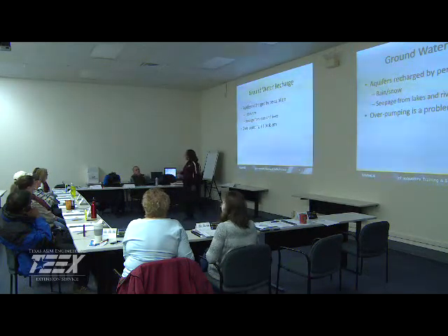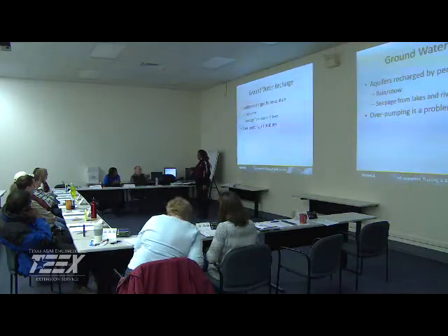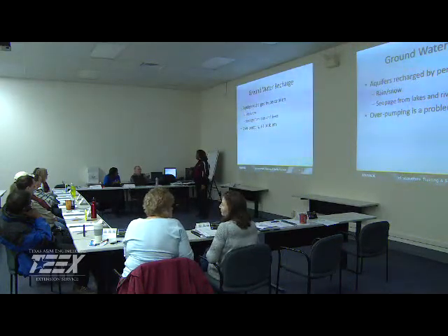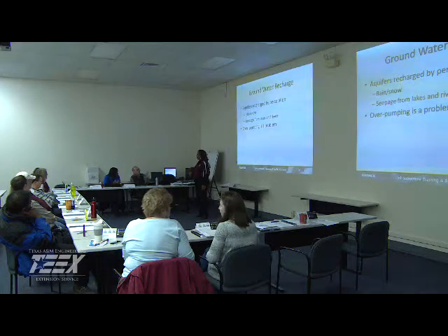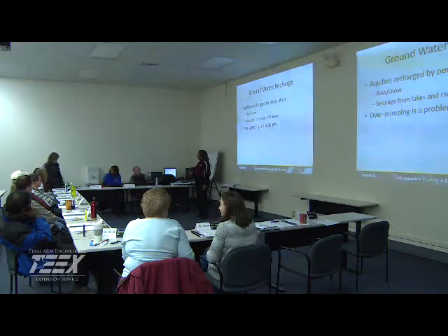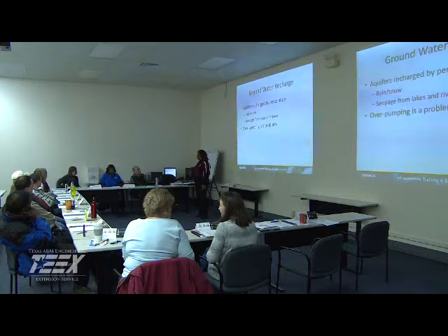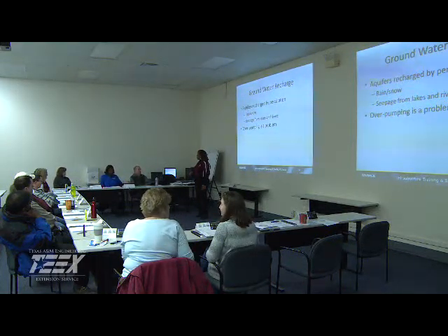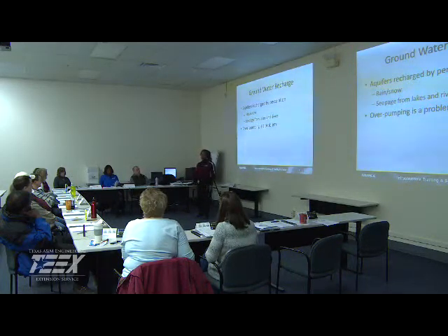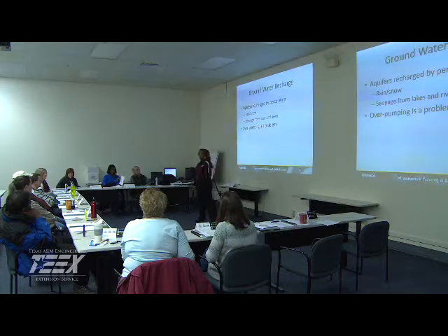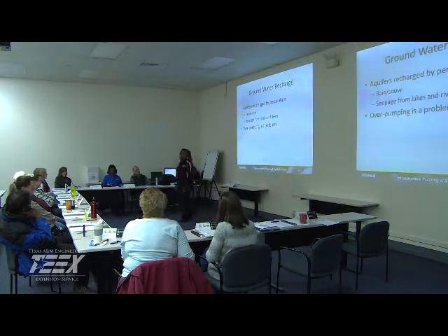In Delaware, they've determined through some scientific studies that when they put nitrates on farmers' fields, it takes 30 to 40 years to get into the shallow aquifer 30 feet down. It takes about 10 years per 10 feet. They've done studies where they look at the different isotopes of the nitrates that were used and where they appear in groundwater. It takes a long time, even with the sand, since you said you all have lots of sand. Yeah, there are a lot of clay layers underneath the sand, which help impede that movement down.